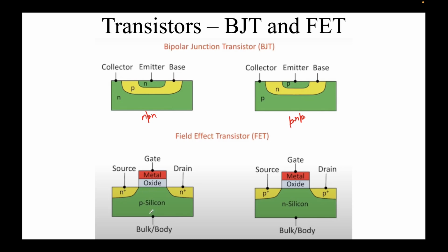Okay, so if you recall, when we inverted that, for a P-type silicon, on this oxide-semiconductor interface, an inversion layer of electrons can be formed, right? And if you can connect this electron layer to these other two terminals, the source and drain, and you apply a potential across the source and drain, the current can flow. So just to repeat, first you form an inversion layer by applying, let's say in this case, a negative potential, VG negative, let's say large negative rather,